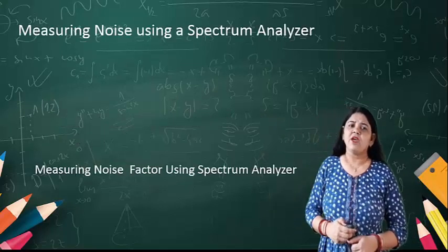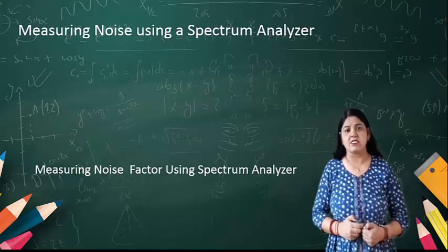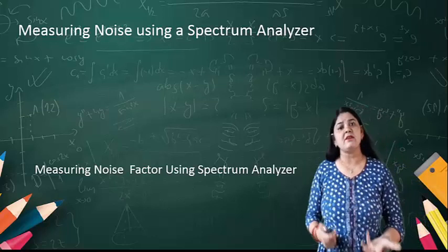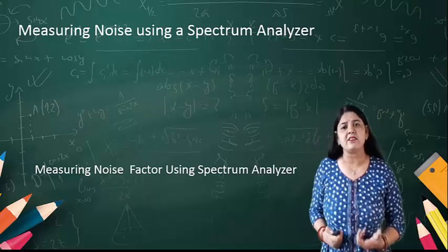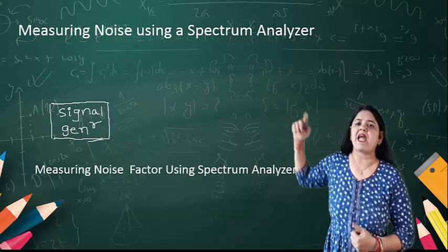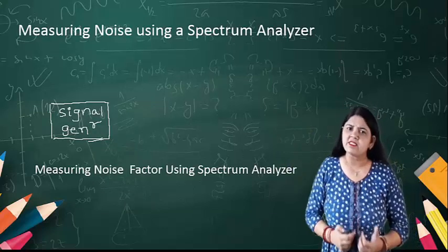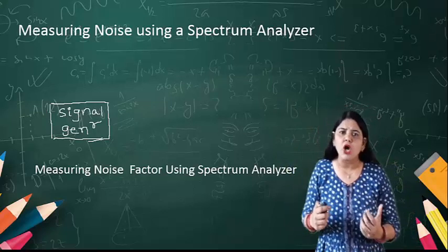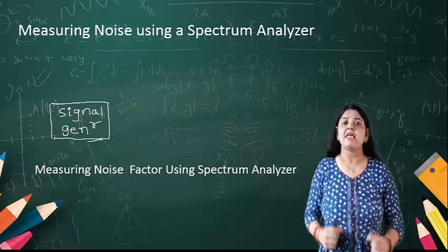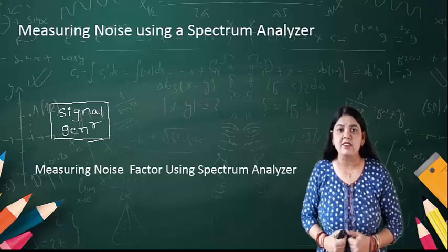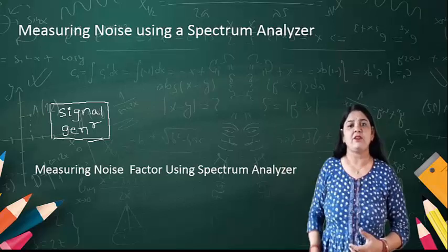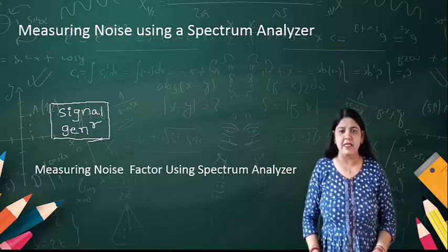Now we want to measure the noise. We have a very efficient device to measure the input signal and the noise level, and that device is a spectrum analyzer. Using the spectrum analyzer, you can easily see and measure all the components, even the minute ones.